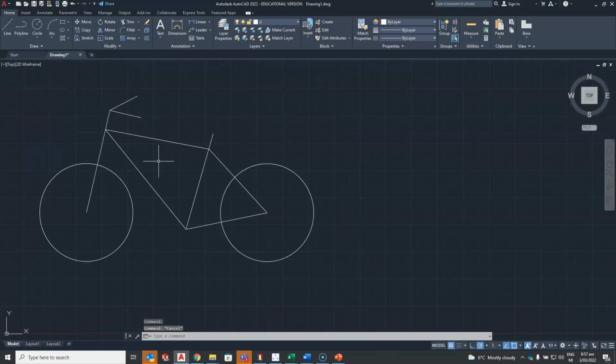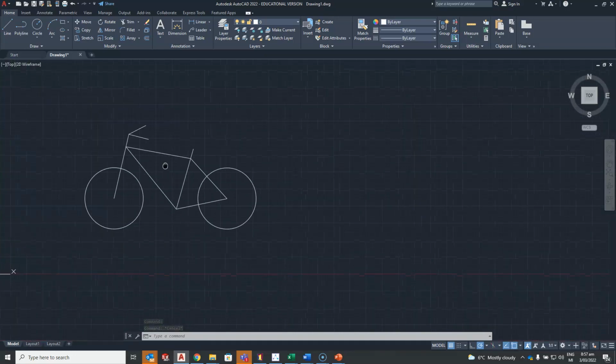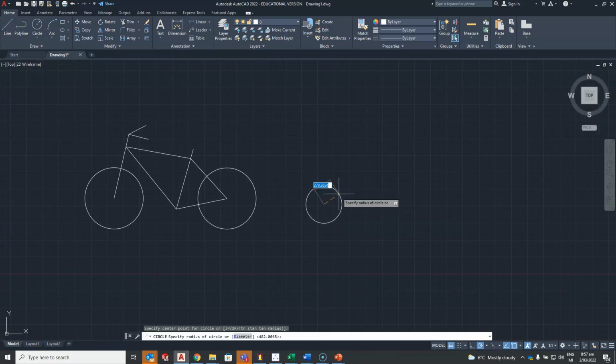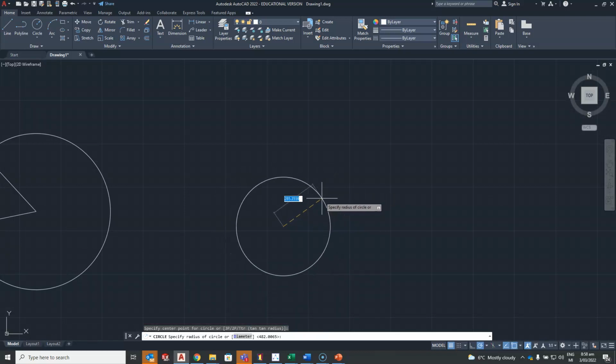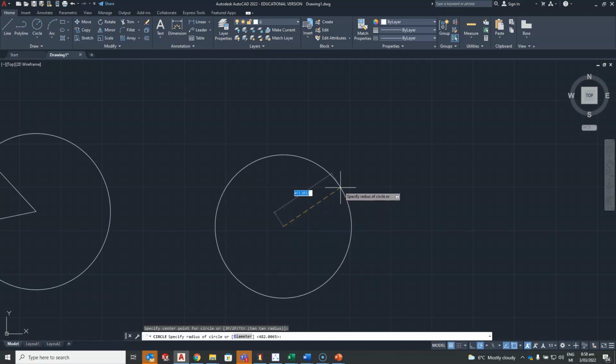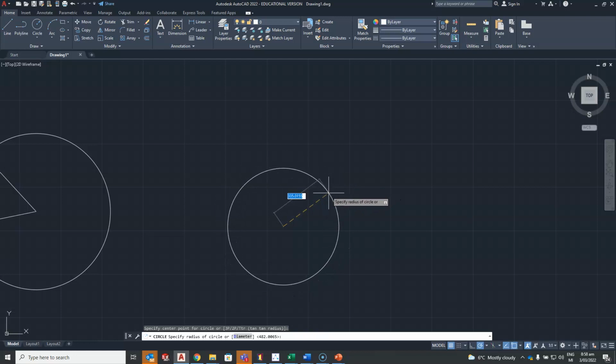So when you start drawing something with some accuracy, we want to key in some information as we go. So if I do that again, circle over here somewhere, you can see the blue highlighted value is changing as I move. Note that it is going from the center of the circle to the edge. It is therefore a radius.